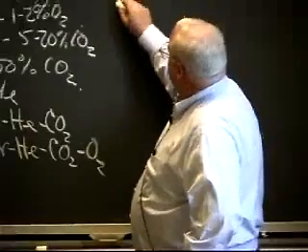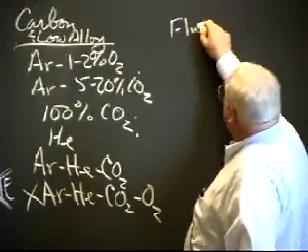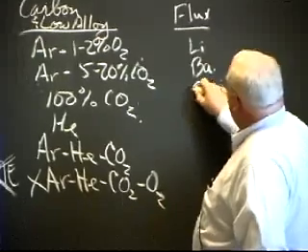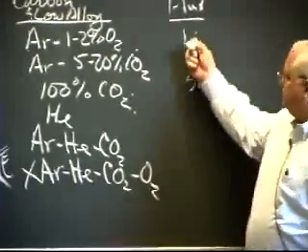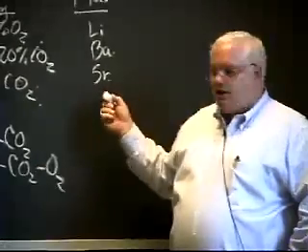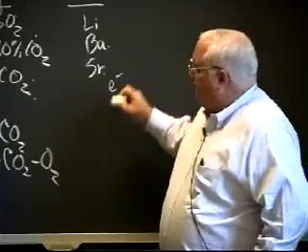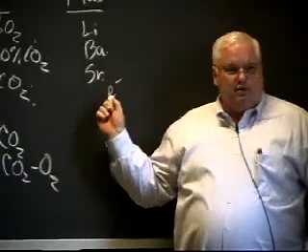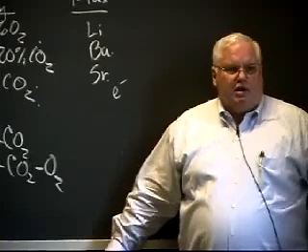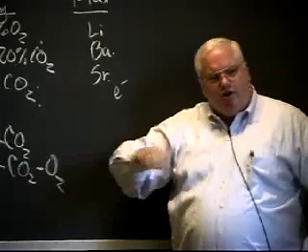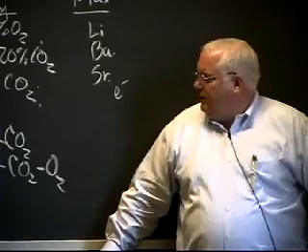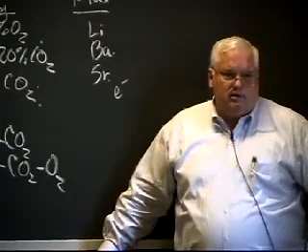If you add lithium or barium or strontium, these are in the first column of the periodic table, and it's easy for them to donate electrons. It's easy to strip an electron off those atoms, and that tends to give easier arc starting. This is actually easier arc running on straight DC, which is a little bit different. And there is no good theory about all this.